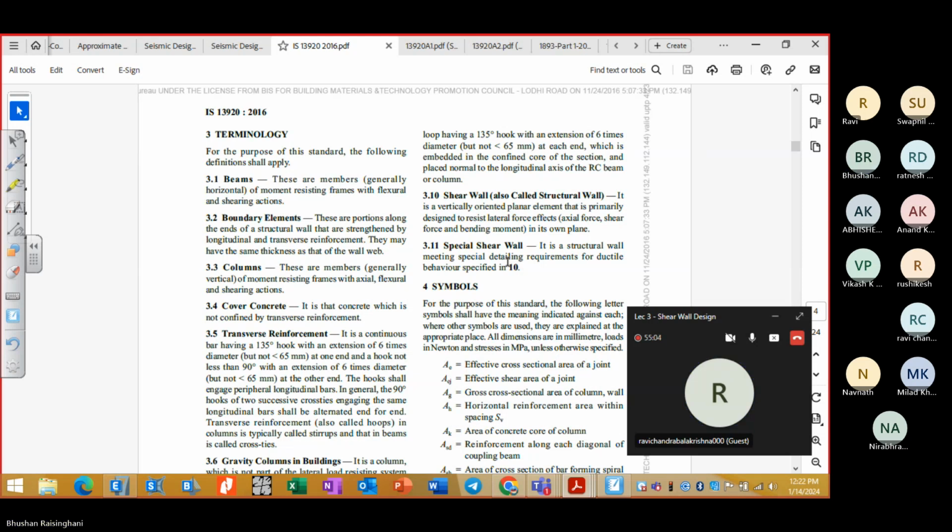So you don't worry about that in-plane moment, there is no option to see it. If you really want to struggle for those things, you go for S11, S12 stresses and look into that. Basically it is only the stress value, the stress contour you will see. You will not get the reactions. That's why we are not using SAP 2000 mostly for the design of shear walls, but for research purposes we use SAP 2000 because it